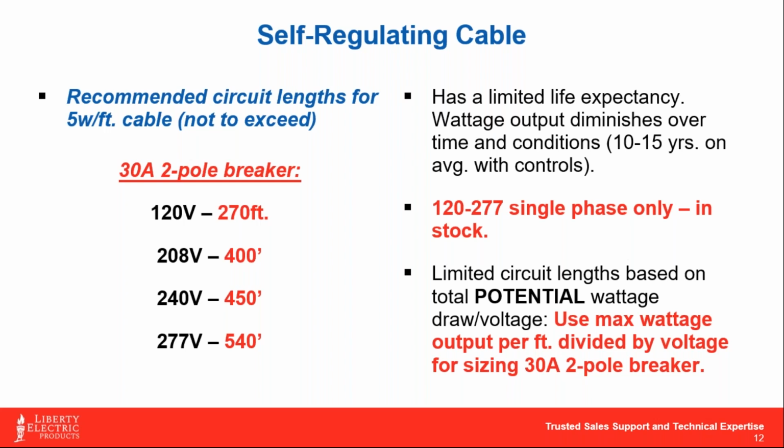But one thing to understand is that heat cable is going to diminish its wattage output over time. By that I mean, if you took a 5 watt a foot cable on day one, by the time you got to, say, 10, 12 years into that process, you might be putting out 4 to 4.5 watts a foot on that cable instead of 5, maybe even down to 3. They can be tested and you can figure that out, but it will diminish over time. It doesn't just up and quit one day unless it was severed.